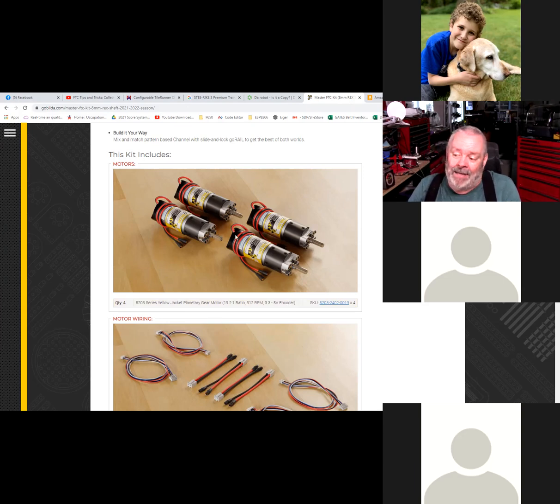Okay, so on the back side of them, you should be able to plug in an encoder. That is a sensor that tells you how fast this guy is rotating. So basically, as it rotates, it'll give you a certain number of clicks per revolution. It's a lot of clicks. It turns out it should be somewhere around 1,120 clicks per revolution. So you can do some pretty precise measuring of things, and that'll help tell you how far you've gone. If you're doing it on a regular time interval, it can also tell you how fast you're going.